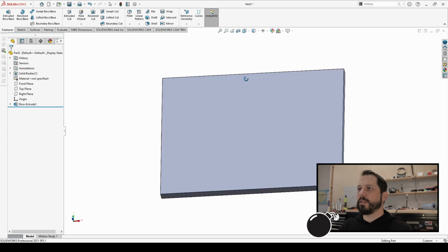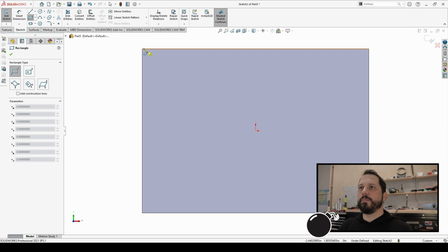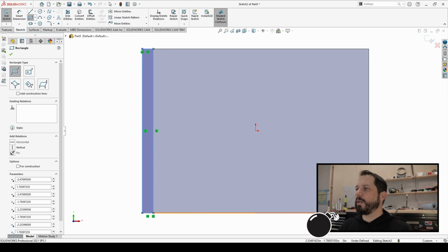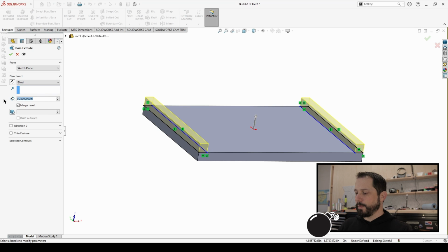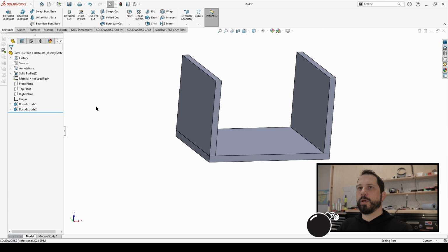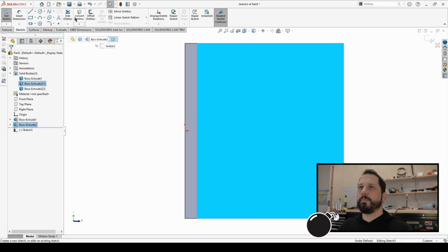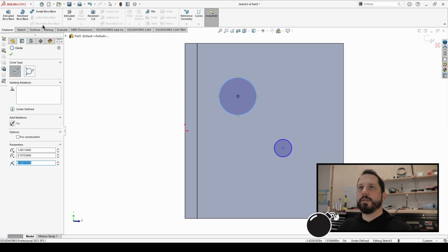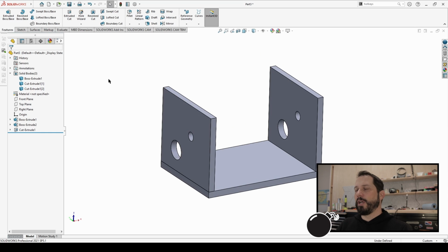So a lot of these parts have just been cut out of 1/4-inch PVC plastic. So what I'll do is say this is the base of whatever housing I'm designing, and I will just, in the same part, so not in separate parts and assemblies and everything, extrude, say 3 inches, but uncheck merge. Then they stay separate, and they are separate part bodies in this part. Then I can keep going, I can have cuts that go through all of them, whatever the design needs. And then I've got an assembly that is super quick to update and manage. This obviously isn't something you'd want to do for a big complicated product.